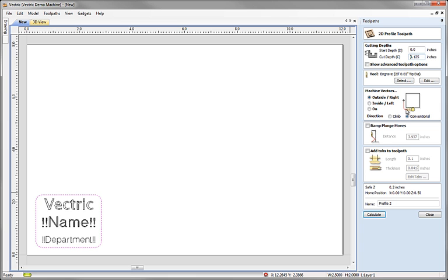I'm going to machine outside of this boundary, and I'm going to add my tabs to this toolpath. And my tabs are going to be very short. They're really just going to be little tiny sprues that I can press out. So 0.1 of an inch in length. Now this thickness I've calculated again using the edit box idea. So this time I want to actually use 1/3 of the thickness of the material. So my tabs can only be very, very thin. They're going to be 1/3 of the thickness of the material.